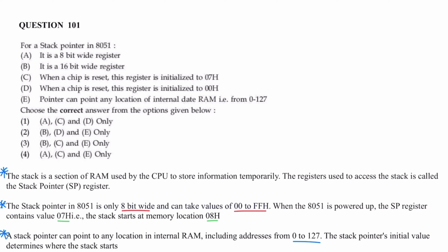The stack pointer's initial value determines the position where the stack starts. So let us see the statements in the given question. It is an 8-bit wide register. So the stack pointer in 8051 is an 8-bit wide register. Statement A is correct. It is a 16-bit wide register. Statement B is wrong.